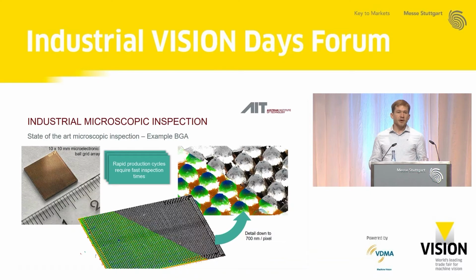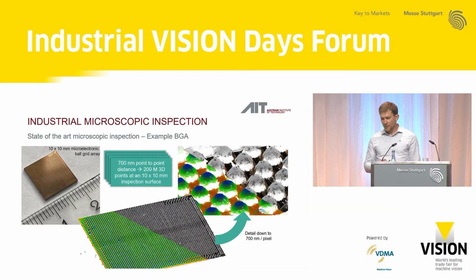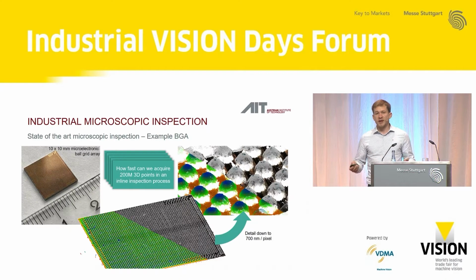And if you think about rapid production cycles, you have to scan such devices in a very rapid way. So if we consider that we would have a sampling of 700 nanometers per pixel, then this would mean for this very small chip of 10 by 10 millimeters that we would actually need 100 million 3D data points. So the question is, how fast can we inspect just such a surface in such a high resolution in a very fast way?